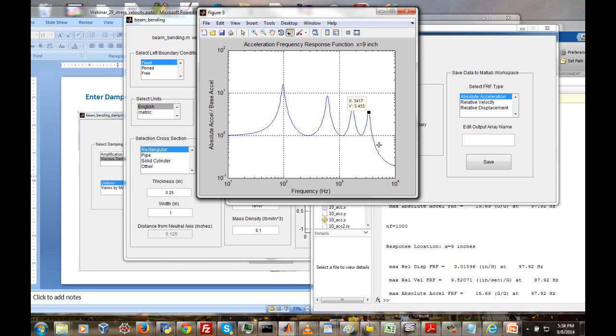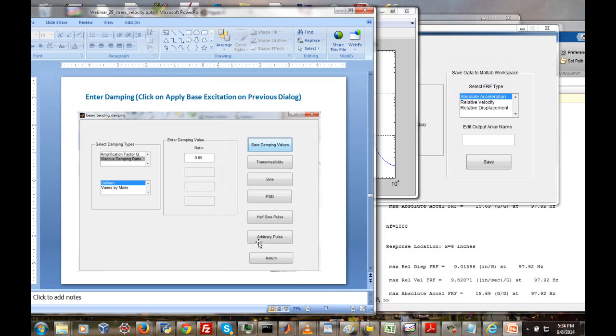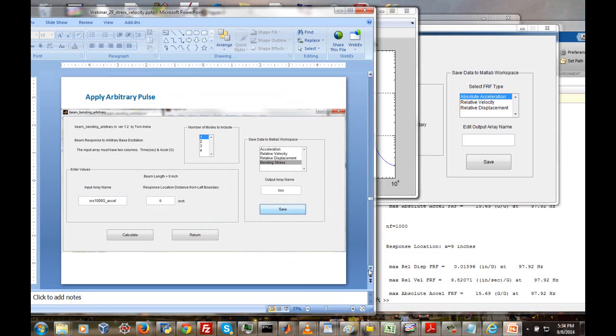And if we do the half-power bandwidth method, we would in fact get a Q equal to 10 for each of those four spectral peaks. So the point is, this being a continuous system, and this is true for multi-degree of freedom systems as well, if we want the Q value, we cannot pick off the peak value at each of the four resonances. Rather, we have to use the half-power bandwidth method. And let me see what the slides have us do next.